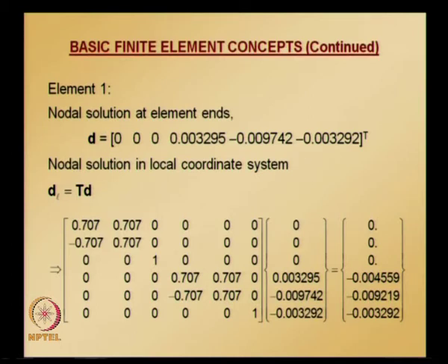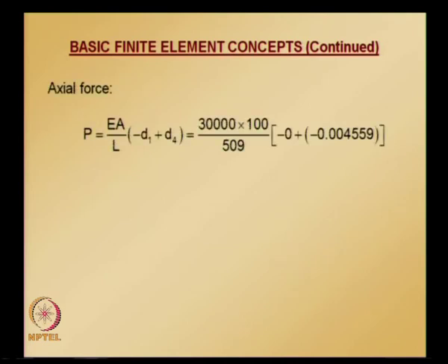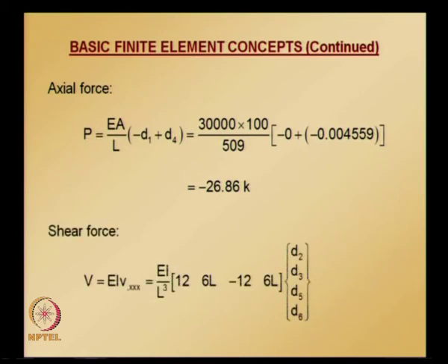And once we get the local displacement vector, or the displacement vector in the local coordinate system, we can apply the formula for axial force. Please note that the degree of freedom in the axial direction for element 1 is 0. Similarly, we can obtain shear force, substituting the values of d2, d3, d5, d6.